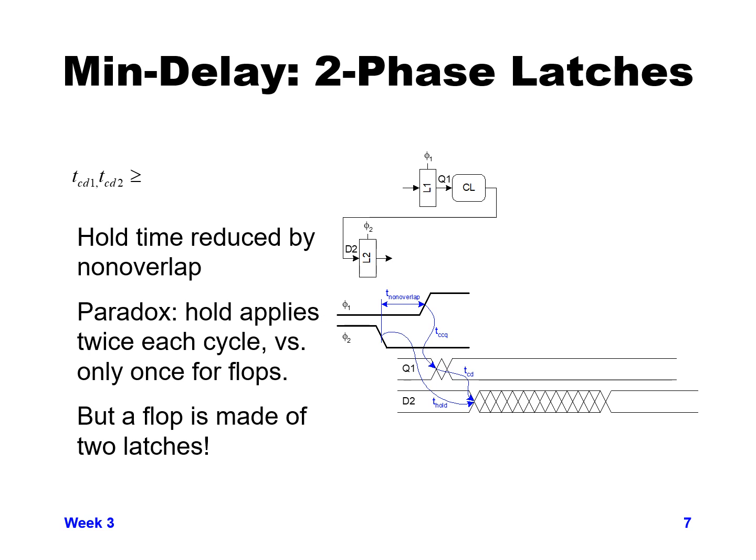But keep in mind, when we use a phase 1 and phase 2 clock, and we have a little bit of additional non-overlapping time where phase 2 clock going low is earlier than phase 1 clock going high, we get an additional amount of time for T hold to help us out.